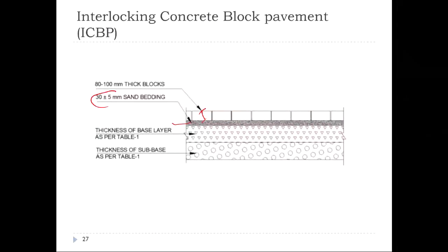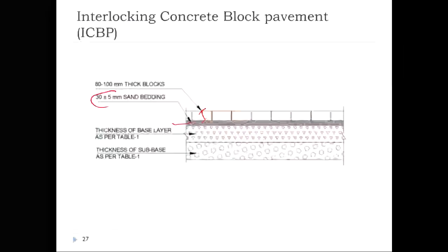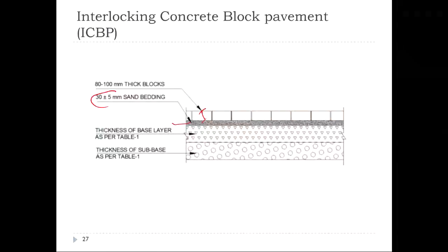Now, as we discussed in the last session on self-fill concrete pavement, the entire philosophy of interlocking block pavements is that we are having shorter slabs. This is in fact a concrete pavement itself, but with shorter slabs of such an order that we are not developing any flexural stresses in the pavement.